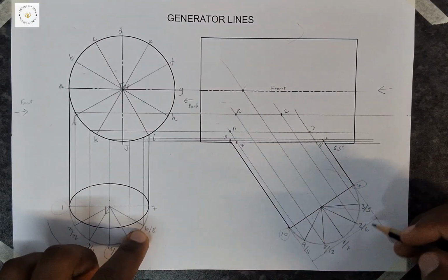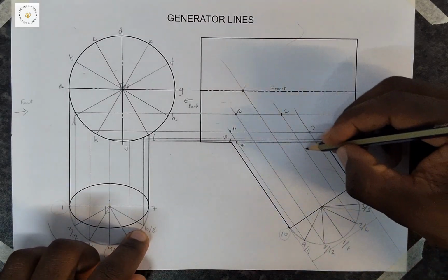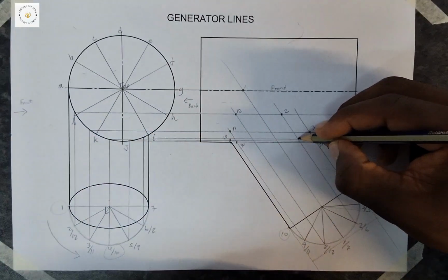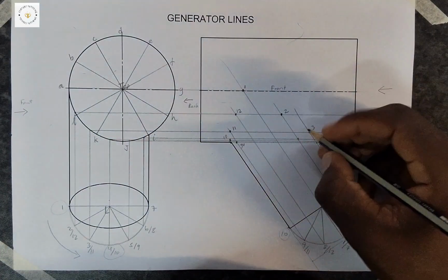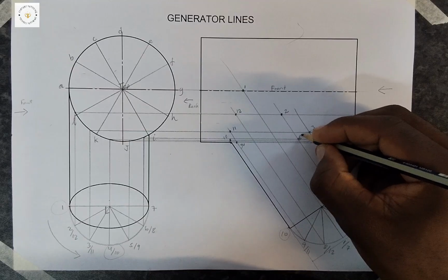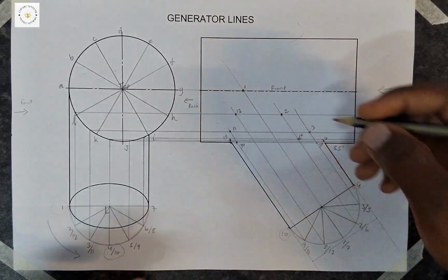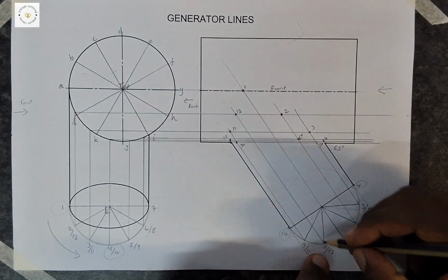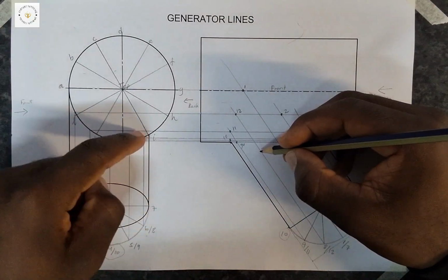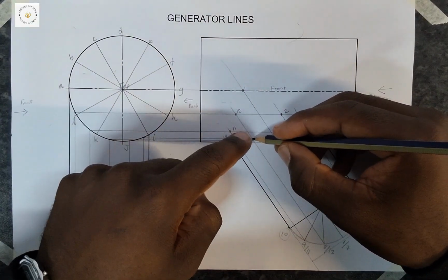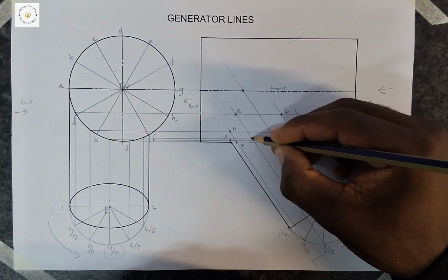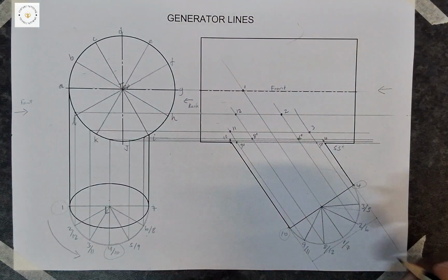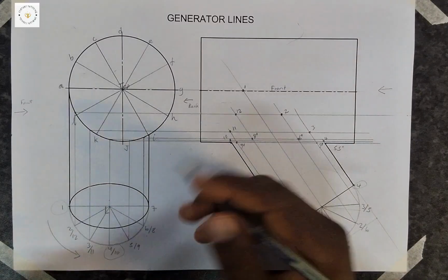So I have that, and then obviously I have to find where 6 is. In this case, 6 is here, and where it meets that, they meet here, and then I make a point. That's gonna be my hidden 6. Remember, it's this side. And then I have to do 8. 8 is here, where it meets the other 8 from the top view. It's here. So I mark that and write that is 8. It's hidden, right? And then the last one is 7.